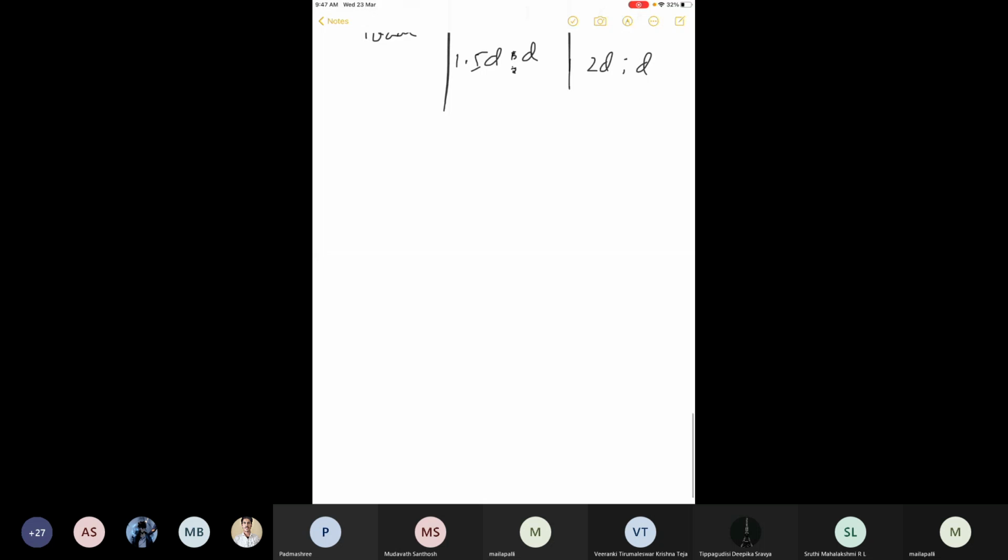With this information, from table number 1 we got the permissible velocity and Manning's n for the particular soil type.